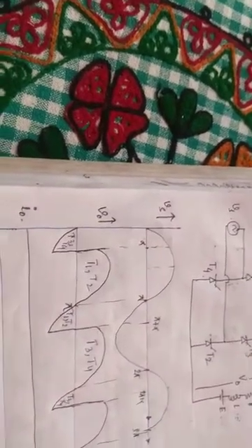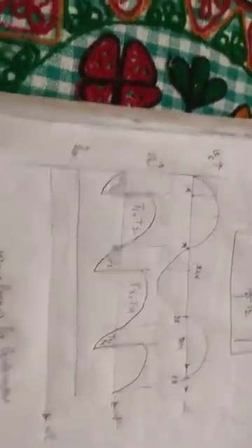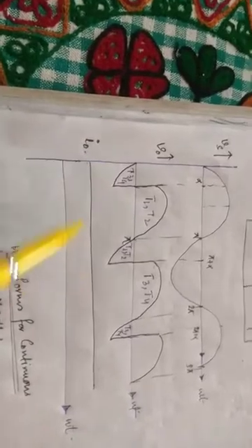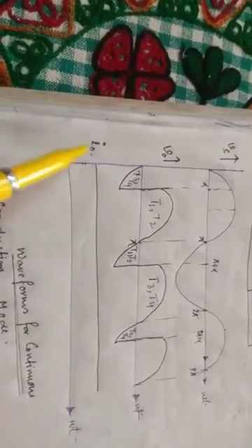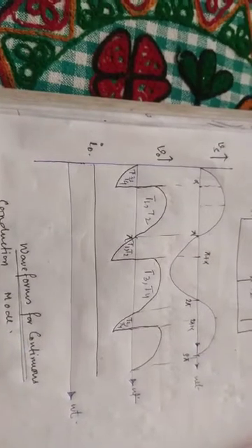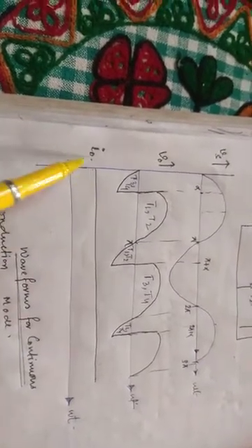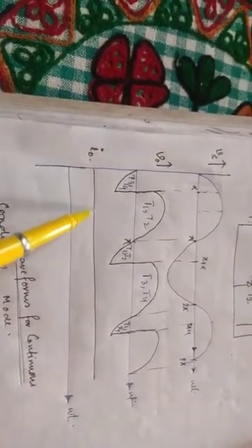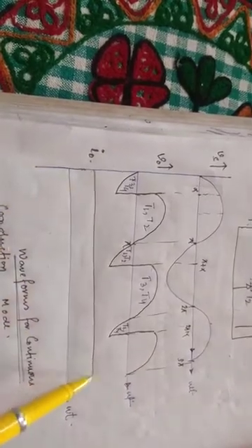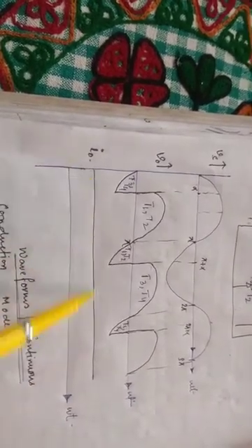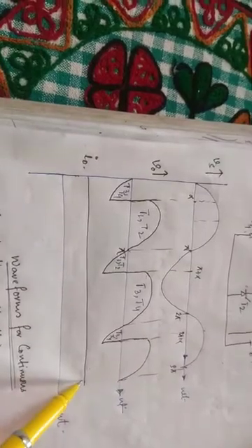Now, this is the output current waveform. Here we have considered the current to be a constant output current, although this is only possible in continuous conduction mode. Continuous conduction mode means the output current does not become zero anywhere; at any instant it continues to remain a constant value throughout. But this is not always the case.